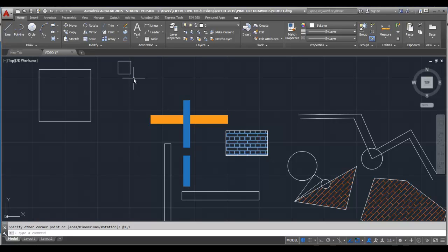It kind of throws you off when it pulls it off into the other side. Let's say we wanted to move this square down into the center of this square. I can take my move tool, select my object, hit enter, find the center point here, move it here, and then hit enter again, select the object, enter, find the center point, move it down. Now watch what happens. If I move my mouse over here, it finds that center point, and I can actually use those two center points to line it up to find the center. It'll actually give me those guidelines. Just gives me a hint.